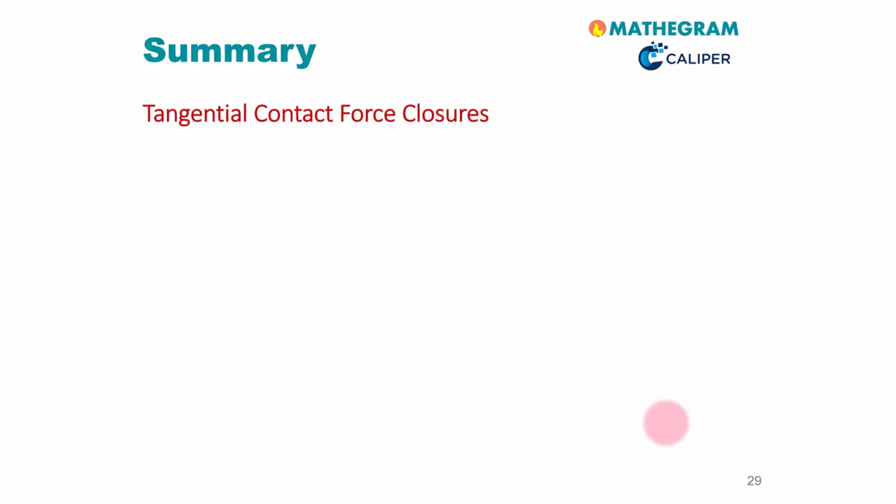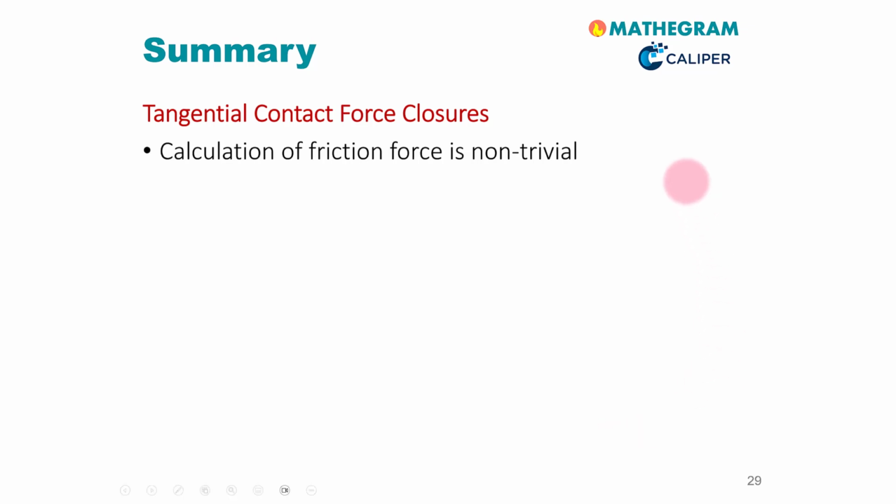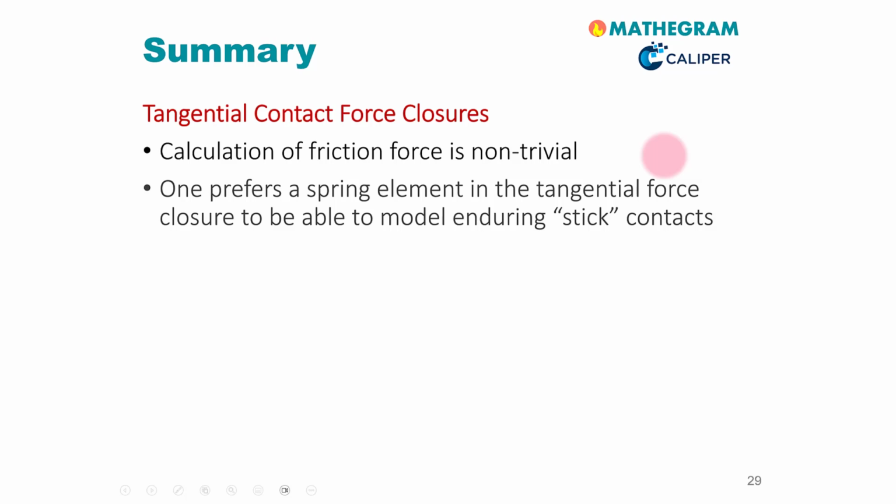If we now switch over to tangential contact force closures, it is important to note that this is a non-trivial exercise. The simple example with the shear forces that I showed you before is a very good start to understand that these contact force closures in the tangential direction need special attention. The last model that I've shown you in the tangential contact force closures uses a spring element. And this is typically preferred because this is the only way to really model enduring stick contacts.